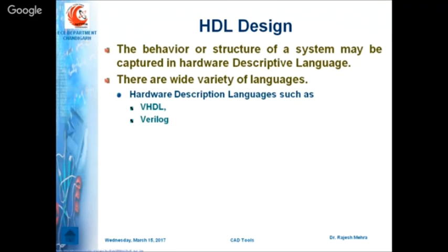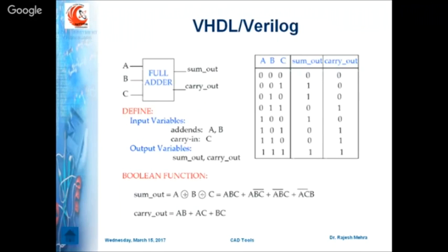And after MATLAB, when you move from the MATLAB environment to the ISE environment, in that case you should have your code in the form of VHDL and Verilog. So normally we use two types of HDLs, VHDL and Verilog, for our design capture.